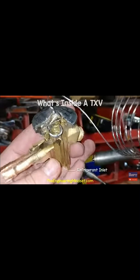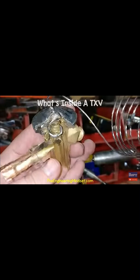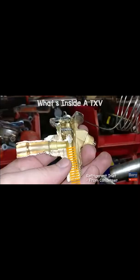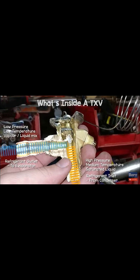We have the refrigerant inlet coming in from the bottom of the main body in this vertical pipe, and then the refrigerant outlet on this horizontal pipe. So the refrigerant comes from the condenser and enters the valve body via the inlet. It enters as a high pressure, medium temperature saturated liquid. It then passes through the valve body, and when it leaves, it exits the valve through the outlet and will now be a low pressure, low temperature liquid vapor mixture.